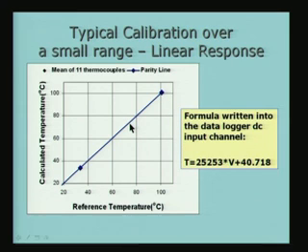For actual calibration, if the low value happens to be room temperature and the high value happens to be, let us say 100 degrees or a little more than that, it is advisable to have several temperatures in between. For example, if you consider this as the full scale and this as the 0 or the reference value, I should have 3 or 4 between these two limits, not coinciding with the end values.